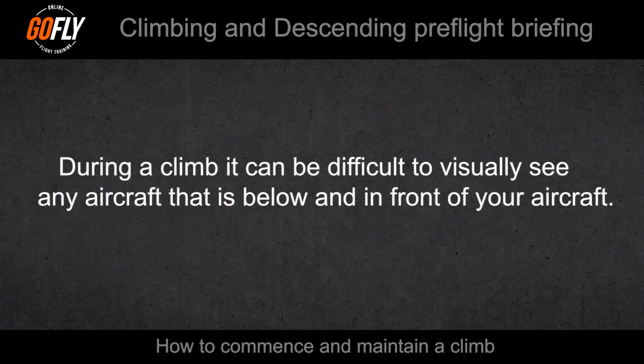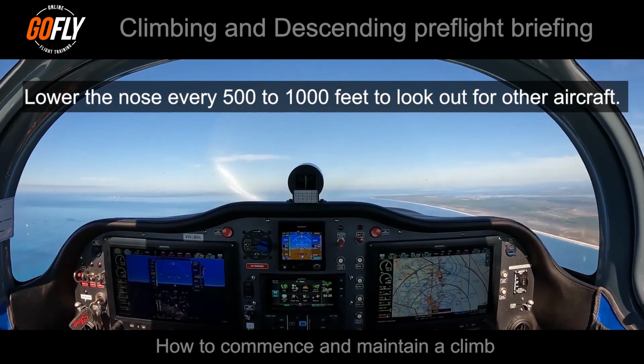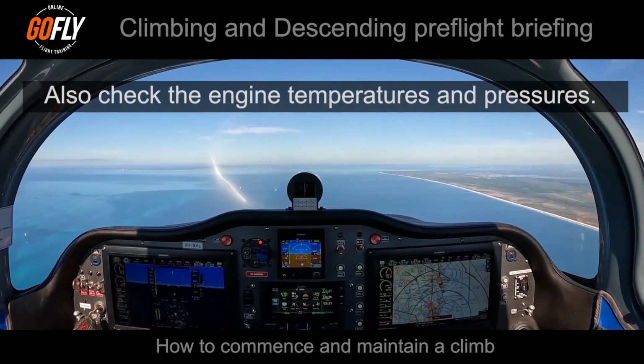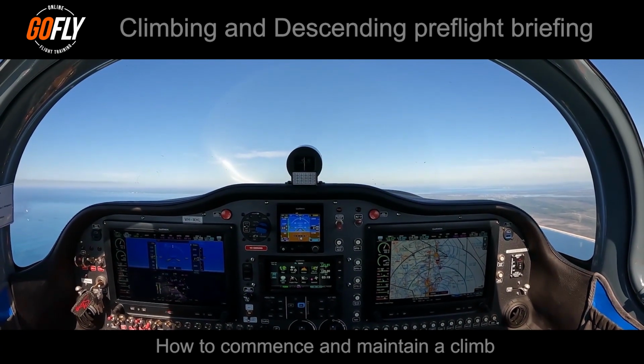When the aircraft is in a climb, due to the high nose attitude, it is difficult to spot any aircraft below the nose of the aircraft that may be on our level or climbing towards us. It is good practice and airmanship to lower the nose every 500 to 1,000 feet, depending on the aircraft performance, and to look out for other aircraft. This is also the best time to check the engine temperatures and pressures. When satisfied that there is no collision risk, continue the climb.